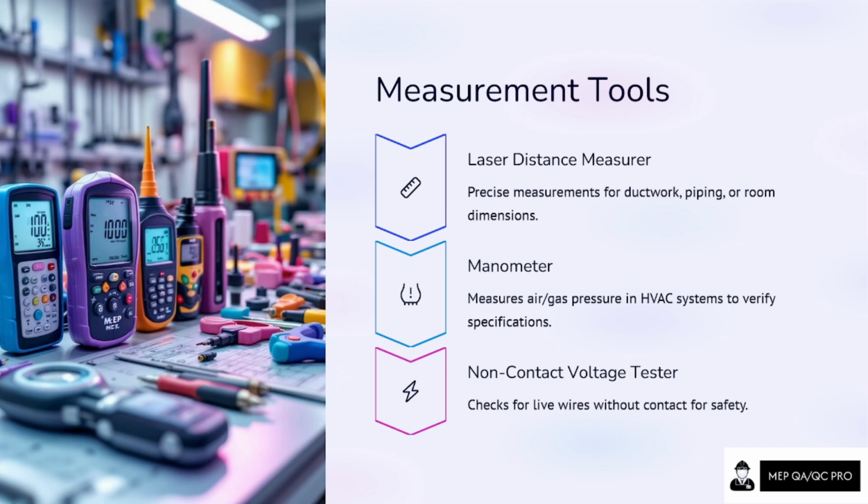Non-contact voltage tester. Check for live wire without contact, for safety. Once the panel is in live condition, for sure there's a safety concern that you cannot check any wire directly which is already live. So through the voltage tester, you can identify which wire is live, plus its voltage, current, and everything, without touching the wires directly.